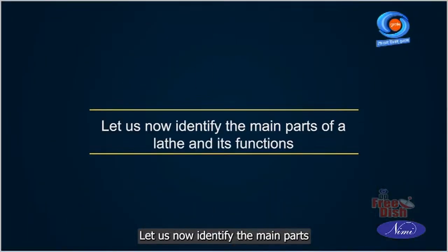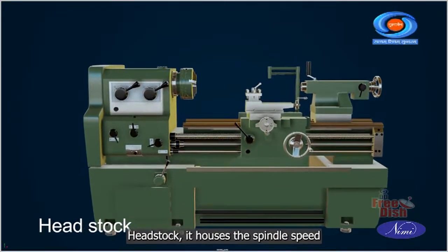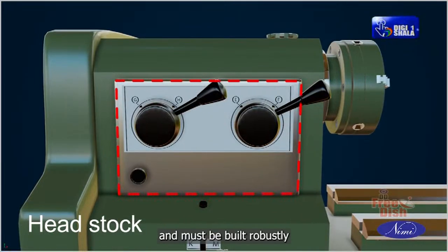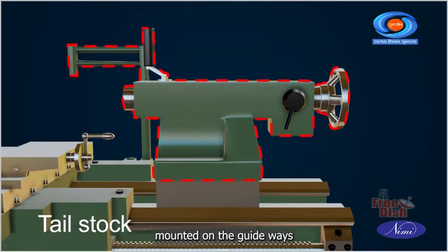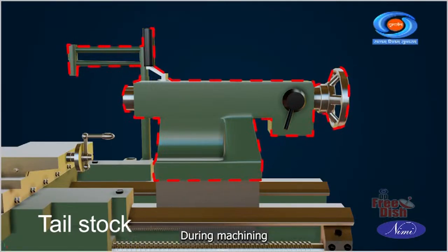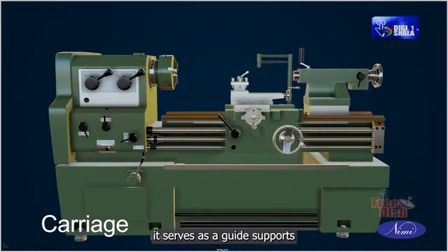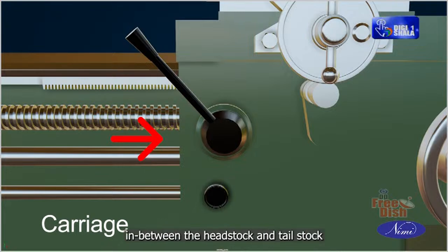Let us now identify the main parts of a lathe and its functions. Headstock. It houses the spindle speed change mechanism and gears and must be built robustly. Tailstock. It is a cast movable part mounted on the guideways of the bed, positioned opposite to the headstock and supports the workpiece during machining. Carriage. It serves as a guide, supports and feeds the tool against the workpiece and is positioned in between the headstock and tailstock.